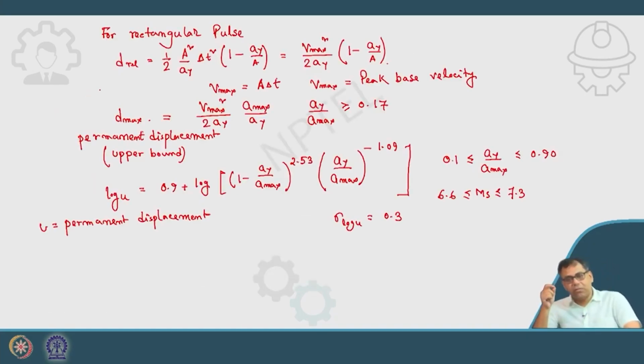And we have already solved one problem in my previous lecture, where under the pseudostatic seismic condition we got a factor of safety equal to 1. As I discussed in the previous lecture, the acceleration corresponding to a factor of safety equal to 1 is the yield acceleration, and there the corresponding acceleration was 0.15 g. So now if I consider the same problem and want to determine the permanent deformation if 0.45 g acceleration is applied, because the yield acceleration in that slope stability problem, where I applied the pseudostatic approach, was 0.15 g.